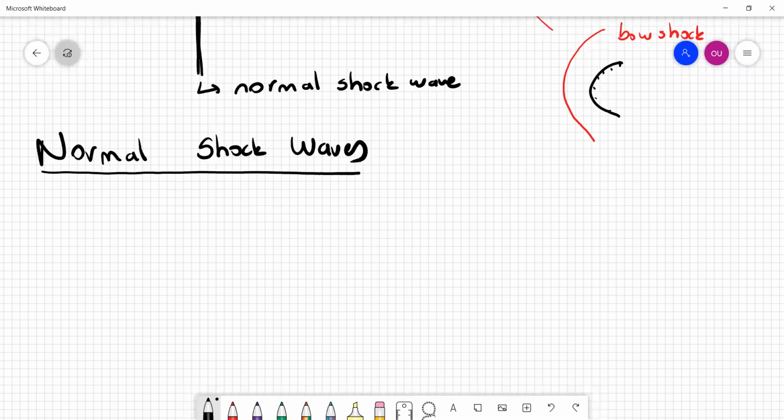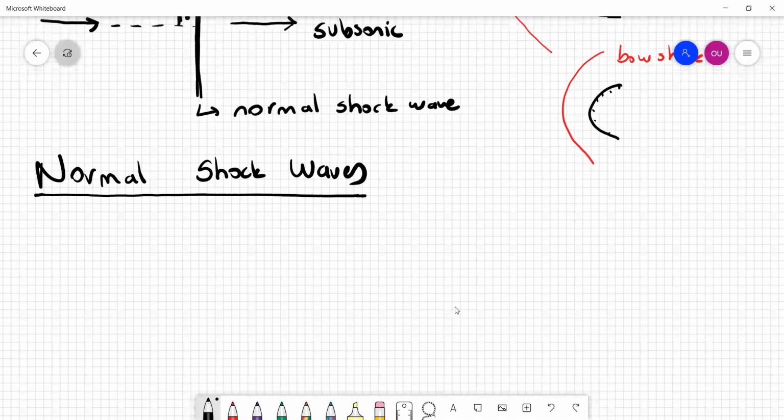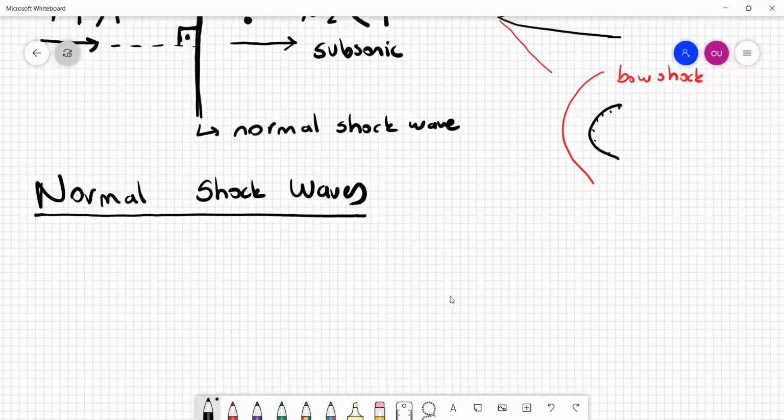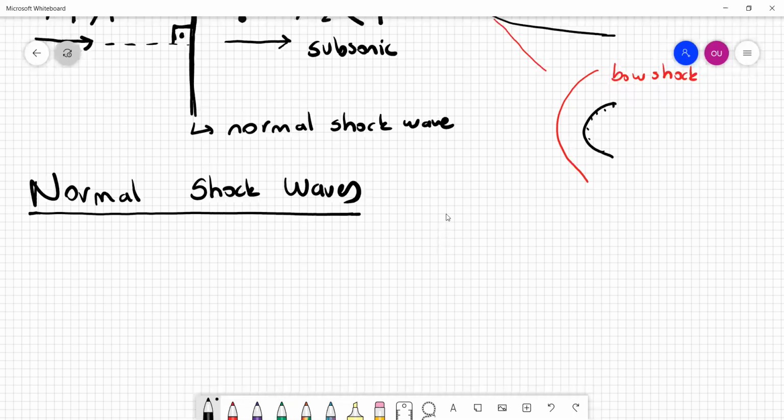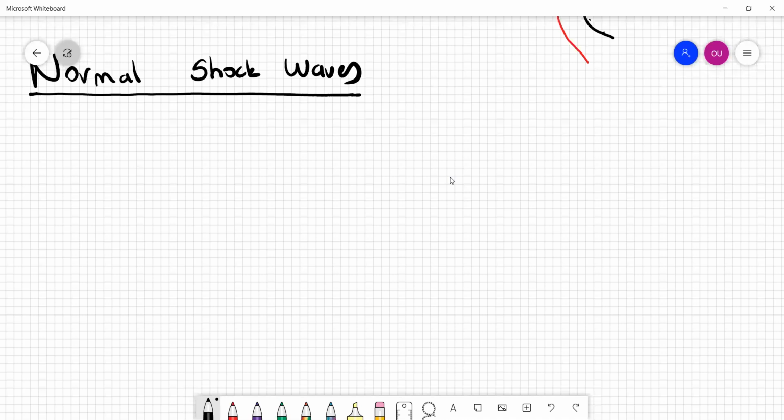Let me see these sketches here. So why is this relevant? We need to understand normal shock waves quite well, because when the vehicle is flying supersonically, naturally these waves occur, but sometimes we also generate them on purpose, especially when we are designing engines, rocket engines, liquid or solid fuel rocket engines. One application, in terms of external aerodynamics, is the flow around a blunt body.